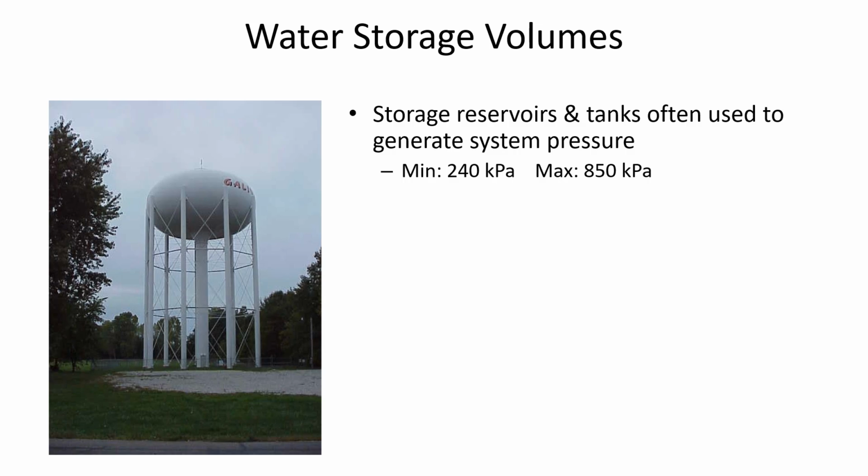So you've done the demand estimation, got the feedback. You've done the pipe sizing. I'm going to be looking at that this week. Next on your to-do list for the project is figuring out how big the reservoir needs to be. In Phase 2, which you've just finished, you decided the location of the reservoir, and by that I mean what its elevation ought to be in order to pressurize the pipe network. But the size of it is also an important factor that's going to influence the overall project cost.